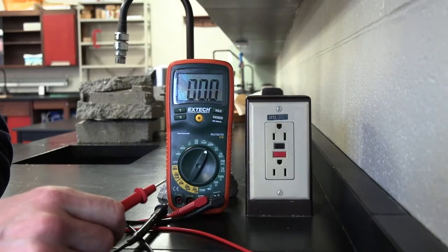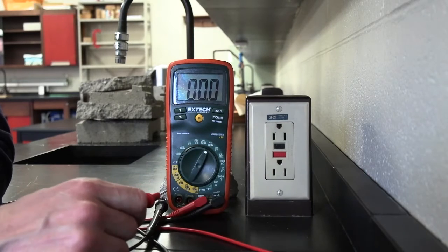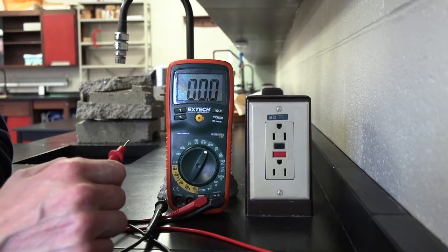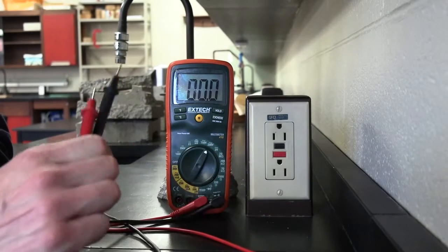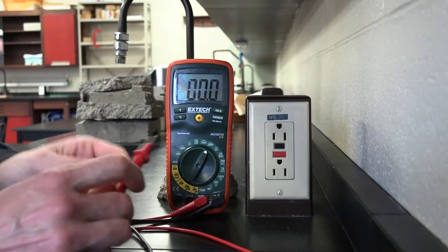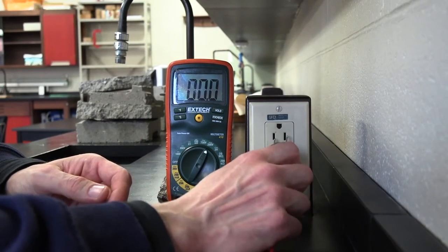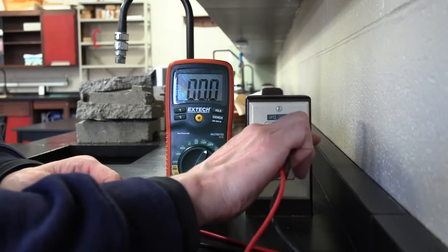Of course, you don't want to do that because electricians do make mistakes too, and sometimes they wire this incorrectly. And so you don't want to find out your electrician that wired your house made a mistake by getting electrocuted. So it's never a good idea to test electricity with your body parts, right? So you want to use something like this, a voltmeter. So now that I have it configured correctly, I'm going to stick the 2 prongs into these 2 outlets to measure the voltage difference between the two, the hot and the neutral.